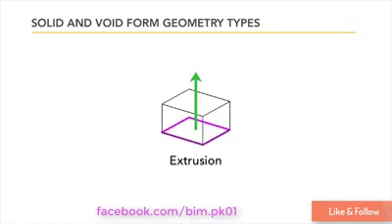It's a basic sketch-based form. You draw out a shape, any shape you like. It does have to be an enclosed shape, so you can't have any open chains of lines or anything, but it doesn't have to be a regular shape. You can make it any irregular shape you like. And you actually can create holes in your extrusion by creating more than one form nested within one another. The only rule is each form has to be closed and they can't overlap one another. But as you can see from my illustration here, it's just basically a form with a height.